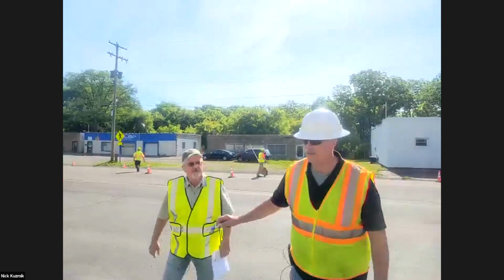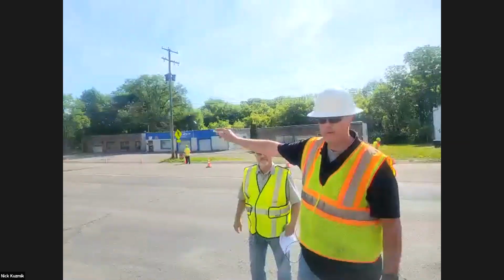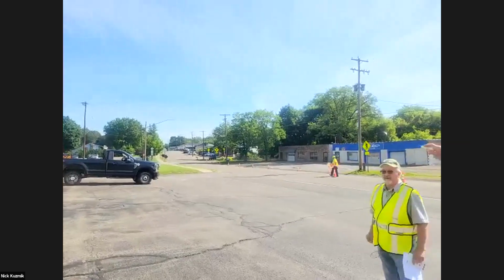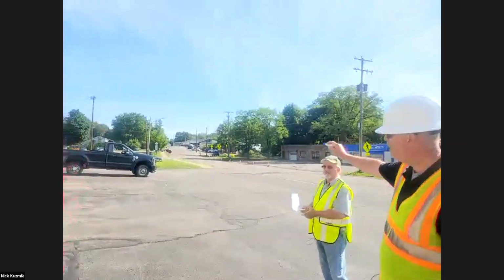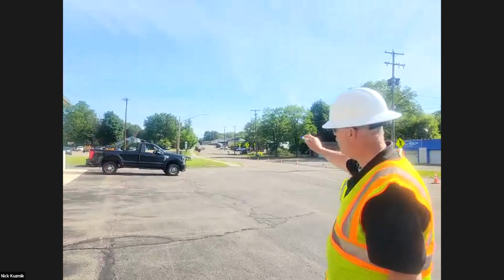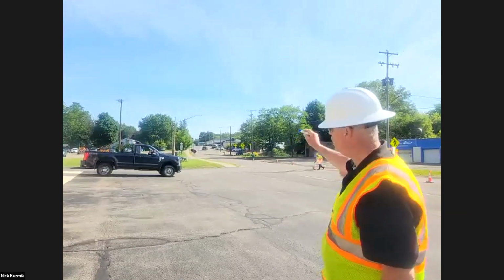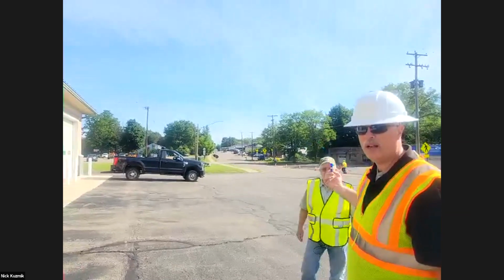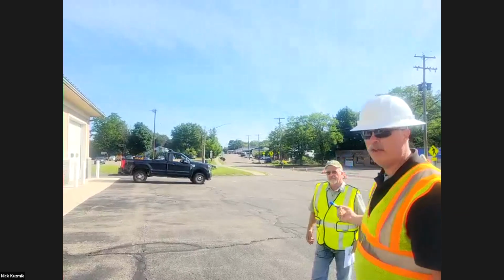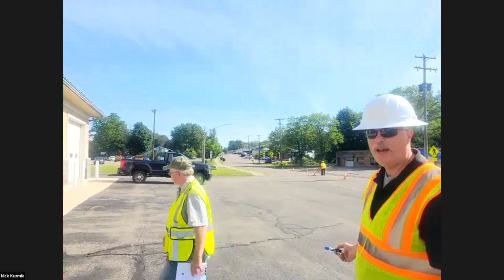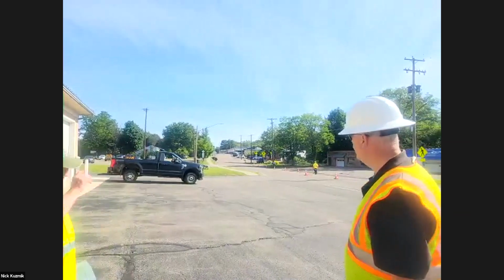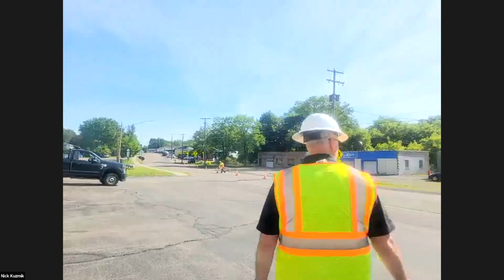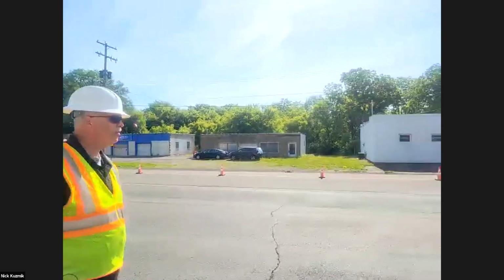So one of the things we wanted to point out, that's kind of like what we're talking about. We got a little rise in elevation at the end of the road up there. Obviously, the work zone is quite far away from that. But if it was a little bit longer and we had to have a little bit more, those signs that we have up there really should be on the other side of that hill, warning people that there's something going on this side. Worst thing you could have is them coming over the hill and all of a sudden saying, oops, I gotta stop, and slamming on the brakes. So I think we're good for here today. With that, let's just watch them set it up here for a minute.